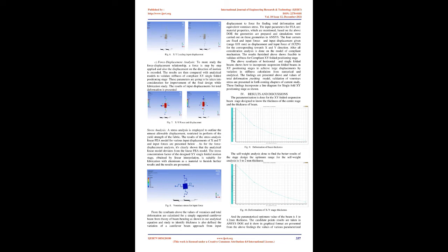C. Force displacement analysis. To further study the force-displacement relationship, a force is applied step by step and the displacement in the direction of motion is recorded. The results are then compared with analytical models to validate the stiffness of the compliant XY single-folded positioning stage. These parameters will be taken into consideration for improvement of the final design during the fabrication study. The results of input displacements for total deformation are presented.